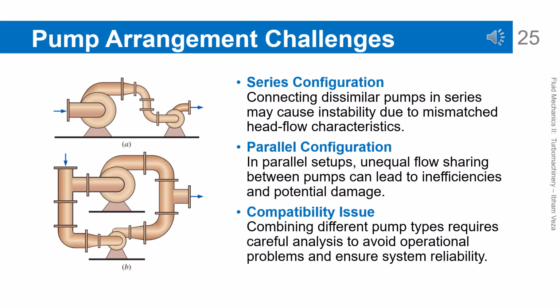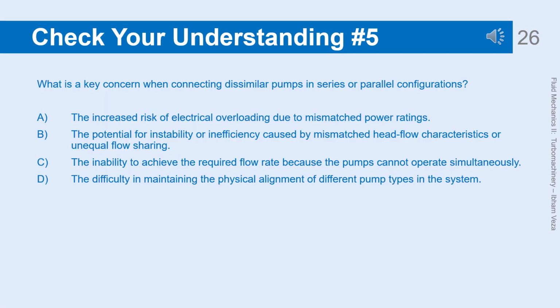These problems arise due to mismatched pump characteristics. Therefore, careful analysis is required before combining multiple pumps in a system. Correct answer: B. The potential for instability or inefficiency caused by mismatched head flow characteristics or unequal flow sharing. Explanation of incorrect options.